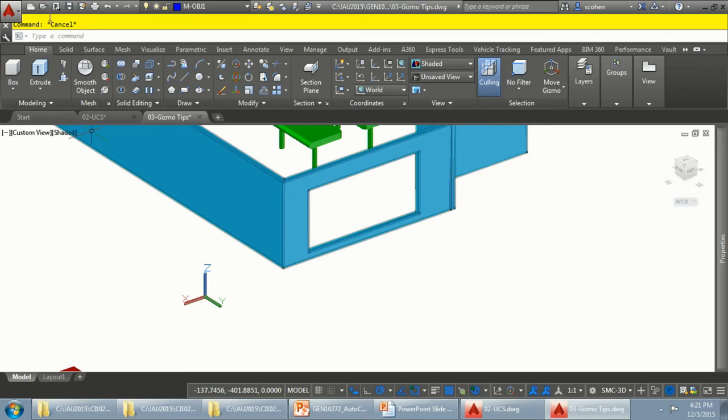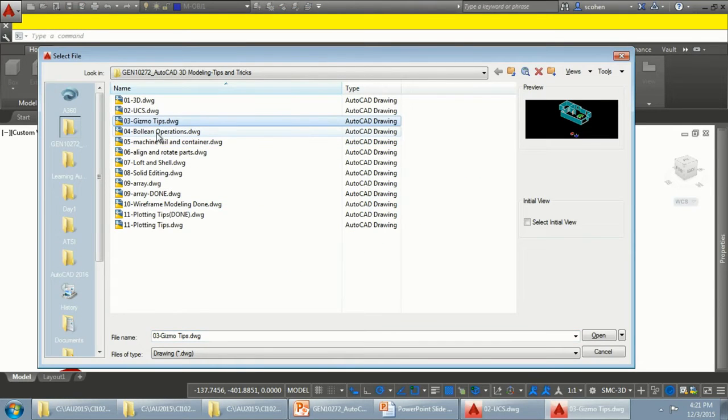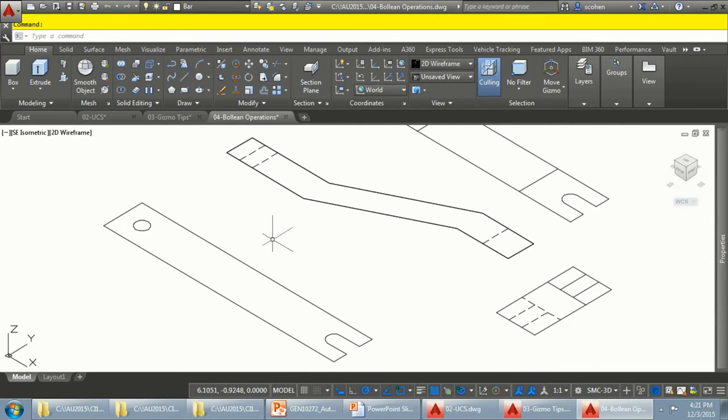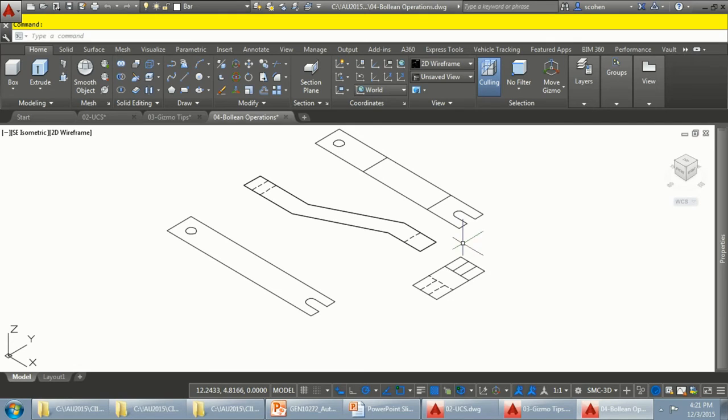All right. Let's look at Boolean operations here. This one here is a cool little example. This is obviously a very simple 2D one. When you see this example, you can use it for some things, but other things you might have to just start from scratch. But let's say right here I've got the top, front, and side view of this part here. To make this a 3D solid is actually not that hard. The first thing I'll do is pull this first up here. Now I don't know the distance, so I'll just use O-tracking. I'll snap here, acquire, and the distance is 3 units, okay?